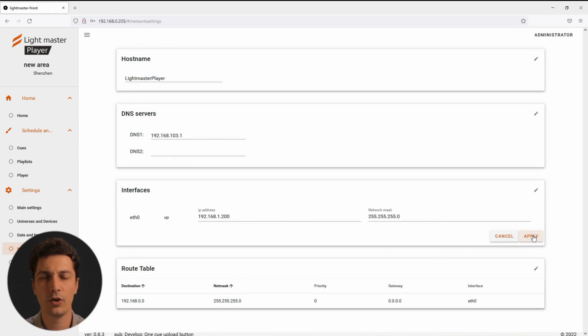If you accidentally entered the wrong address, made a mistake, then simply reset the power. At LMP, turn off Unplug from network to ensure safety. Then switch the power on again. The IP address will be restored. To confirm the updated IP address, you must modify the network card settings to place it in the new subnet again.